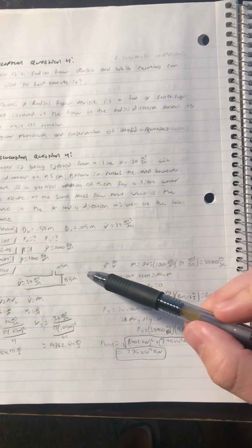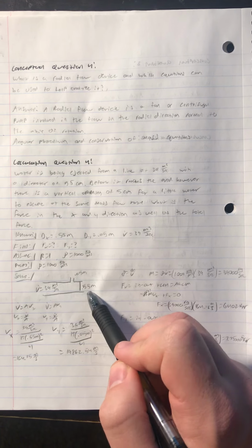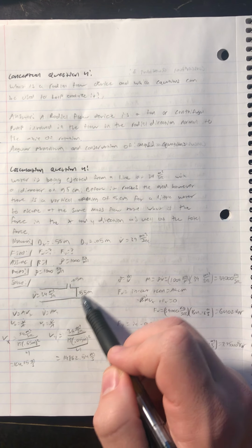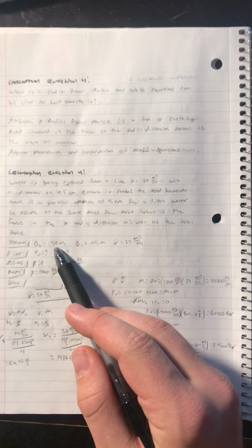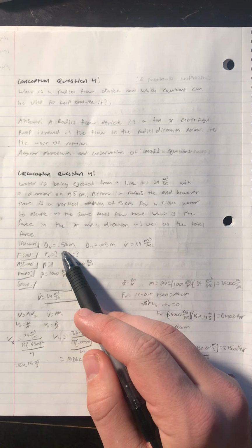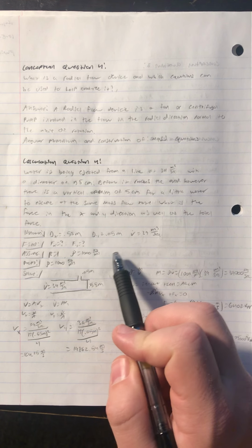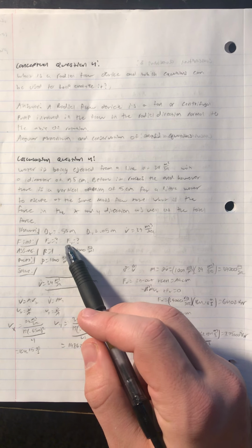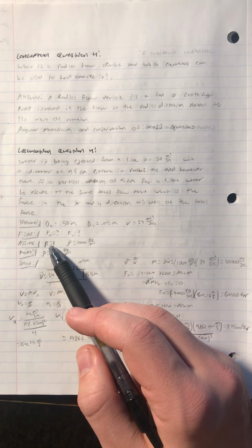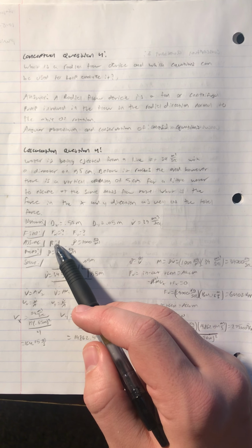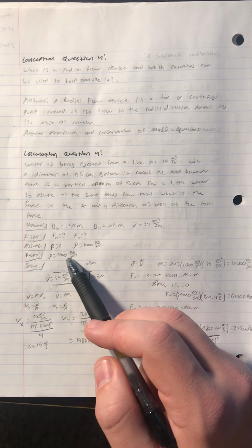So we can look at our picture here. There's a flow rate coming in at 39 meters cubed per second, and it's ejected here and here at the same flow rate. And then what are the total forces from this little picture? So our knowns are the x diameter is 0.55 meters, the y diameter is 0.05 meters, and the volumetric flow rate is 39. We're looking for Fx, Fy, and then the total F. We have to assume a correction or beta factor of 1 with a density of 1,000, and that's also a property.